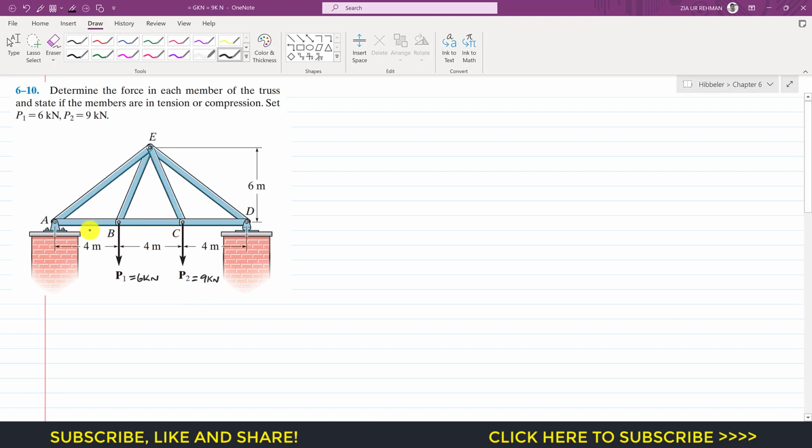So first of all, we need to consider this whole truss and we need to find the support reactions at point A and D. So at point A, we will have two reactions. This one will be, let's say, AY, and we will have one horizontal reaction. Let's say this is AX. And at point D, we will have only the vertical support, right? So this is DY.